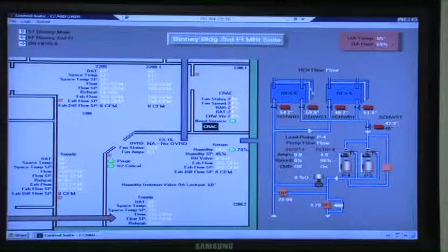It's just one heat exchanger. So this one's online right here, I'd guess. The other one's for the 7th floor, right over the common. They're common, it's one big loop system. So one's in standby and one's online, correct? Well, to be honest with you, I know that the pumps will lead-lag, they'll alternate based on a rotate schedule. As far as the heat exchangers go, I'd have to check them and see. It might be manual. We don't physically have any isolation valves that switch one heat exchanger to another. So if it's going to be something, it's going to be a manually switched valve-type heat exchanger setup.